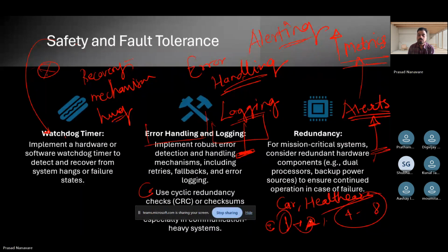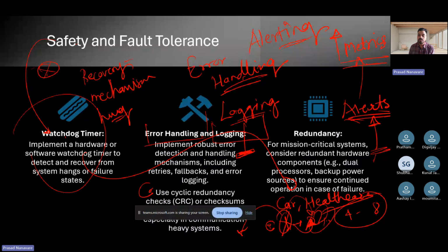Because the watchdog can do this thing as well. It is watching basically what is happening in the entire system. If certain errors are there, and in the form of an alert we get alerted that, hey, this sensor is not doing good, what we can basically do is disable this, and completely switch to the other sensor which is good in health. That's why having redundancy in place is any time a better option. Basically you are delivering a double of the systems that the consumer ordered in a single enclosure.